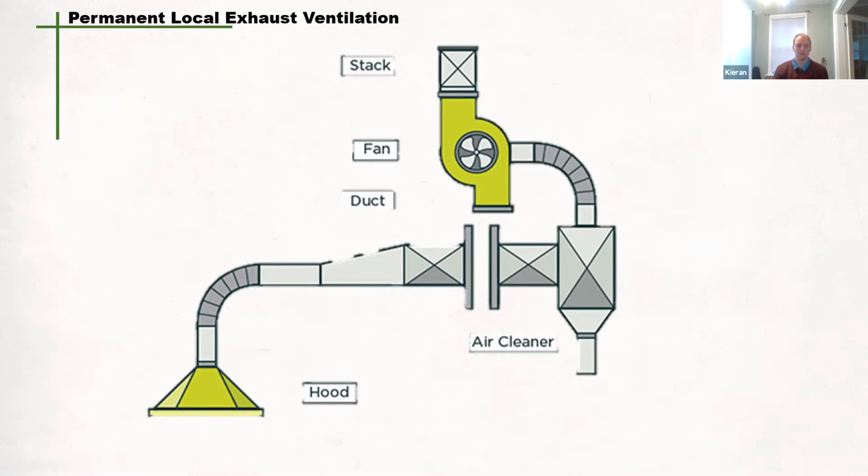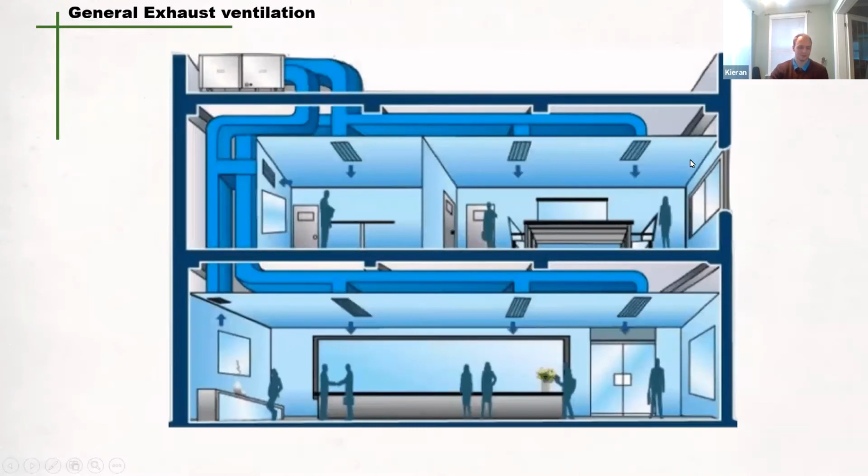So these are really good when there are bigger particles that will settle more quickly, the toxicity of the contaminant is high, like welding fumes, environmental conditions are extreme, and the cost of heating large volumes would be excessive. So if you have one welding operation in a shop where that's the only time it happens, it may not be worthwhile to get rid of all of the air all of the time. So this is a solution for there. We'll move on and look at general exhaust ventilation.